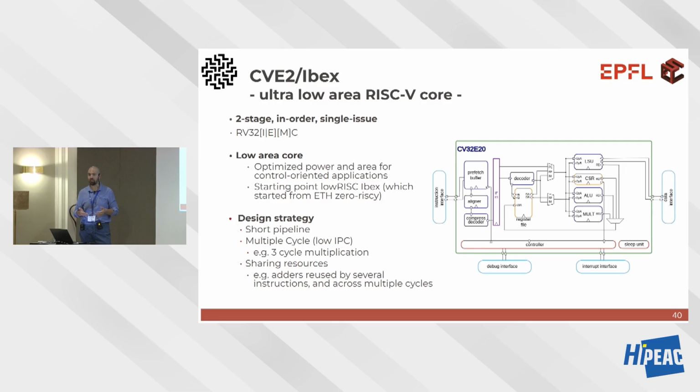But if you are mixing them, if, for example, I have an instruction at the address 12, and the next one is compressed, so it will start at 16, and the next one will start at 18. Because it's only 2 bytes. So when we fetch a word from the memory, 32-bit, we don't know if the instruction is starting at bit 0 or at bit 16. We don't know it. Correct?